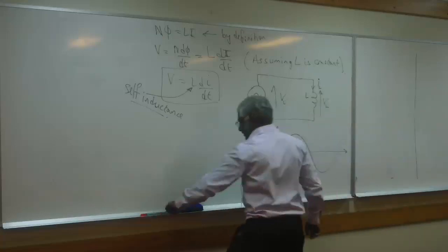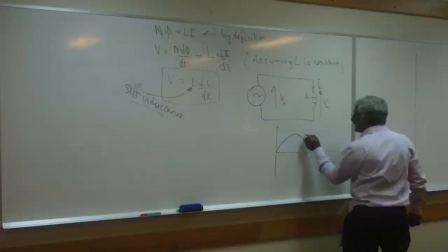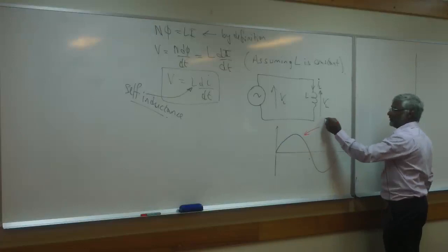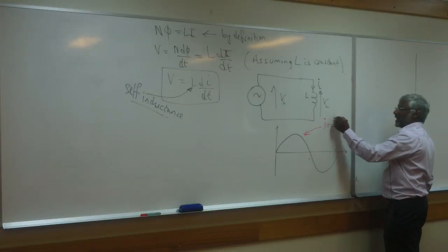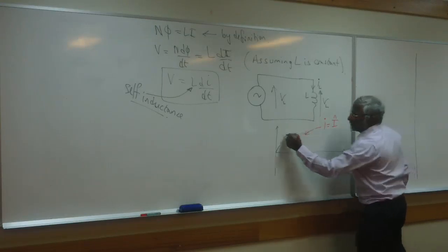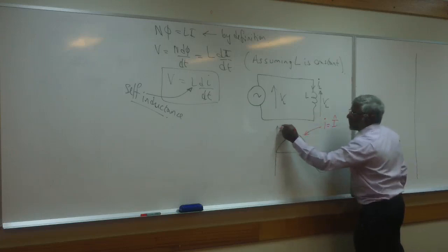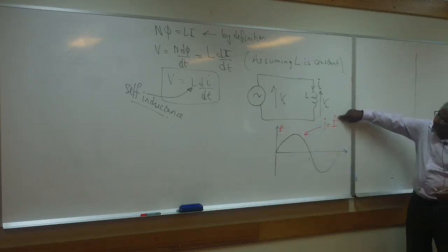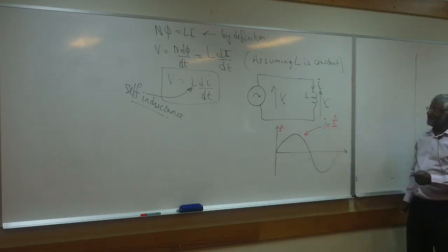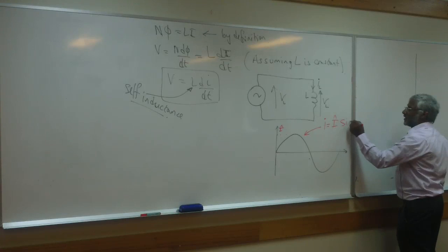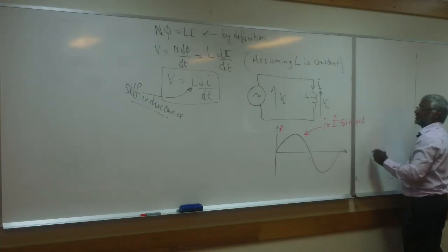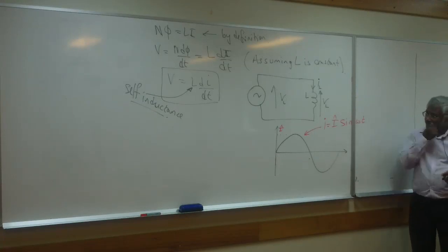So it's a sine curve. So the current I is a peak current. That's a peak current there. This here stands for peak, and the formula would be I peak sine omega t. So that's a current.